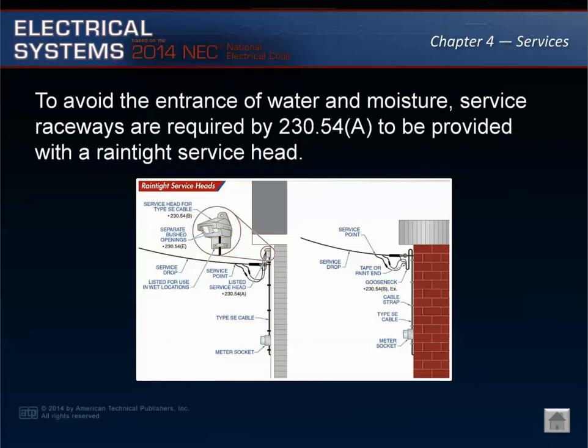To avoid the entrance of water and moisture, service raceways are required by 230.52(A) to be provided with a rain-tight service head. The rain-tight service head shall be installed at the point of connection to the overhead service conductors or service drop and shall be listed for use in wet locations.